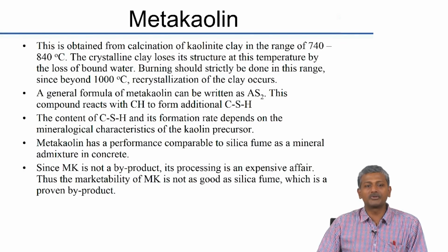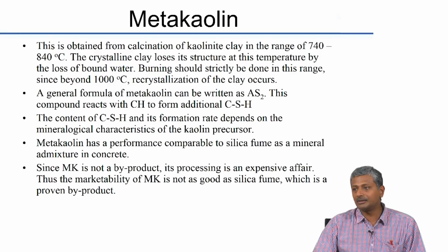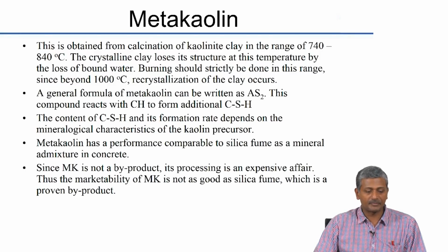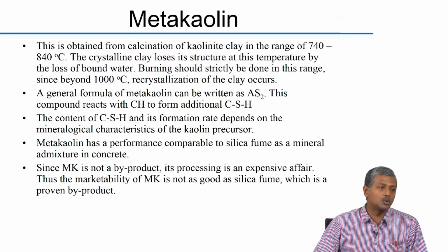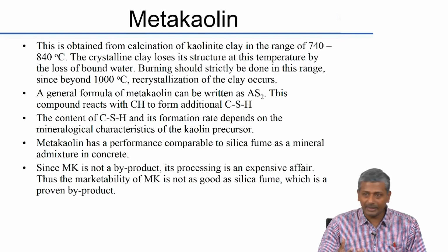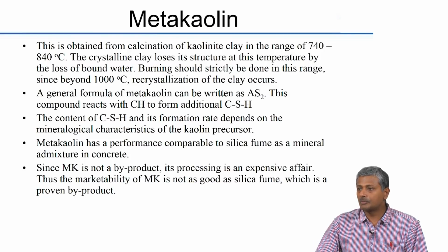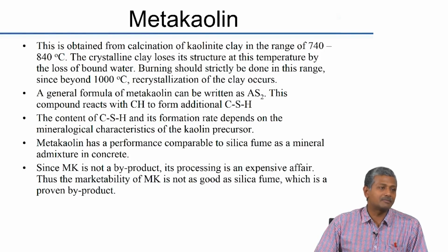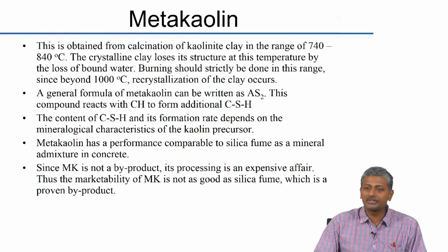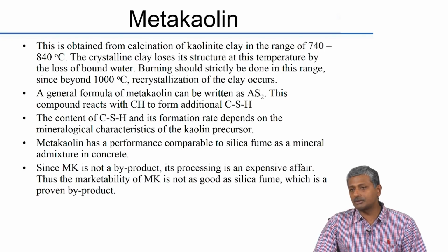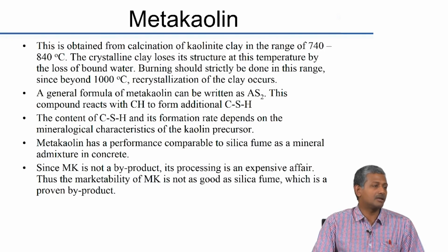And since clay is aluminosilicate, you again get mainly a pozzolanic reaction from this system. Of course, please remember here what you are doing is you are collecting the clay and then burning it. So, there is a major processing cost involved. Processing involves burning of this clay, and that sometimes takes up a lot of energy, and because of that energy the cost of that material can be significantly large.